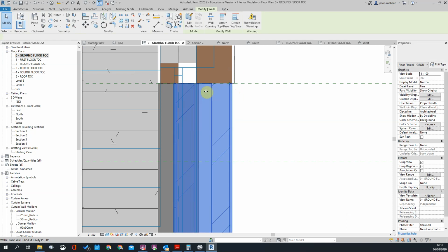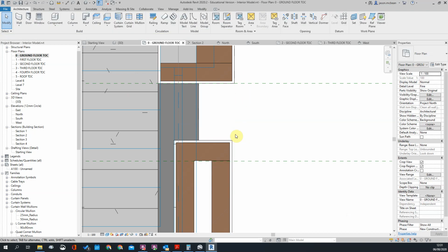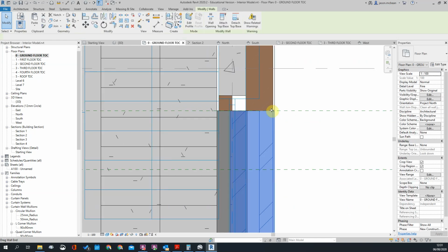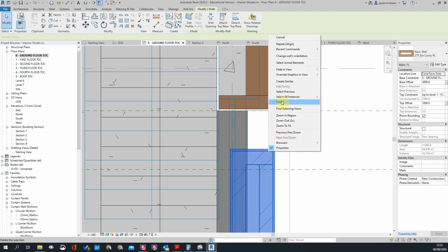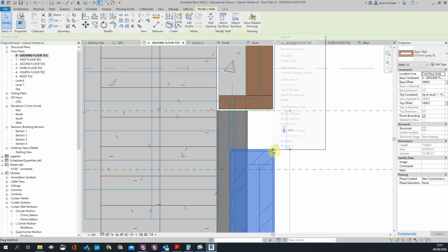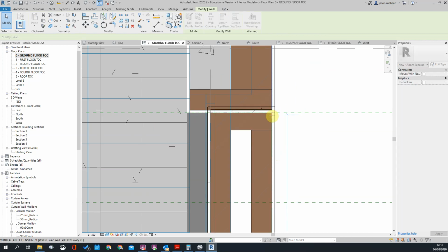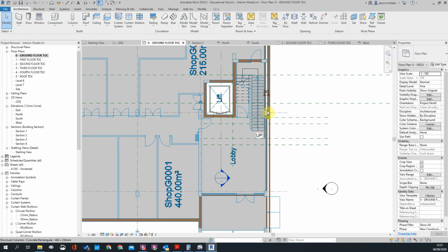Let's not do this. These little details where they join here, this does get tricky with Revit. So there's a lot of little techniques that we can use in this area. But we'll have a look in a minute. We can see what we can do, like how these join. So I tend to disallow join. So if you click on this blue dot, I'm going to say disallow join. I'll show you how we join these a bit later.